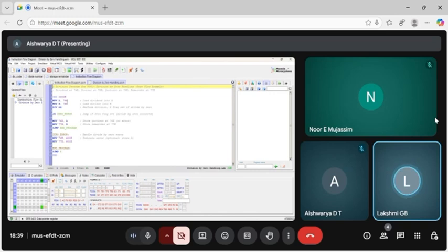Handle division by 0, the error label. MOV 76H, #00H. MOV 77H, #00H. Stores 00H at both addresses to signal an error. End of the program. End program: SJMP $, and the program enters an infinite loop marking the end.